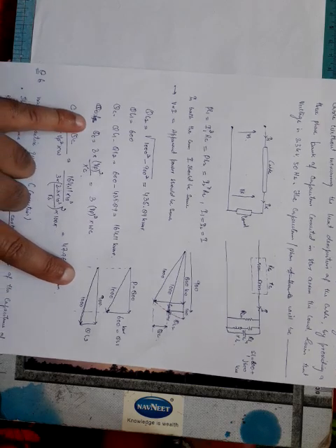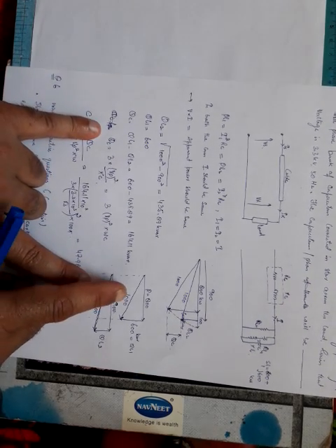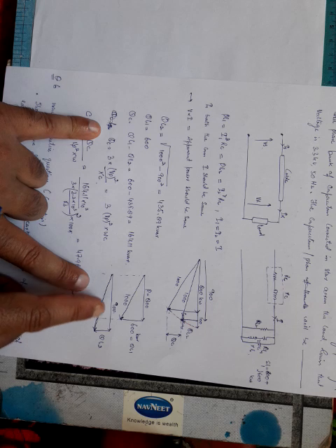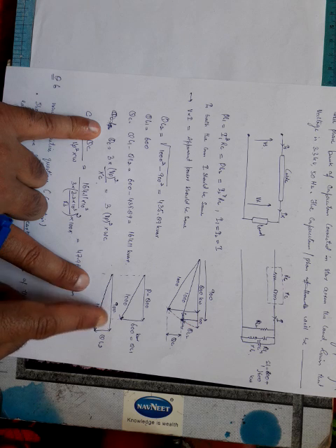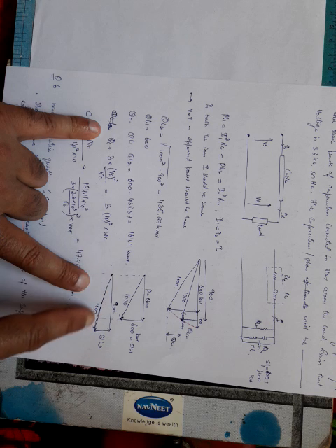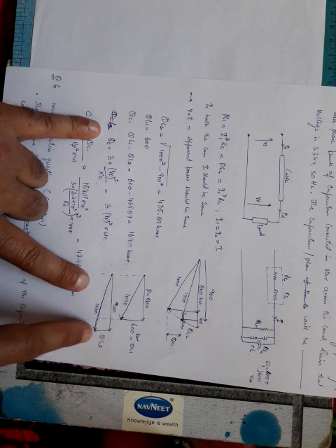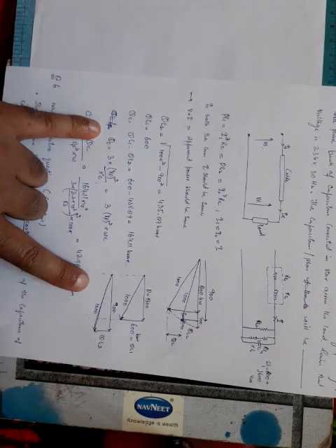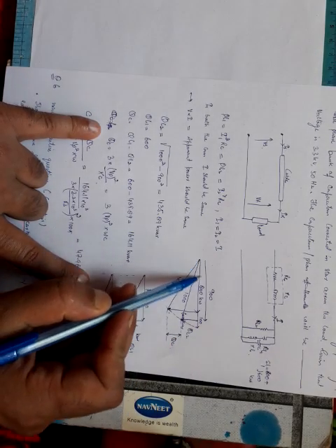Now in the second case, we have to keep this apparent power the same, that is, this 1000 should be the same, but this has to increase. While doing so, when this increases, this remains the same. It means this QL2 has to decrease as compared to QL1. You can see it from here. This is the first triangle like this.